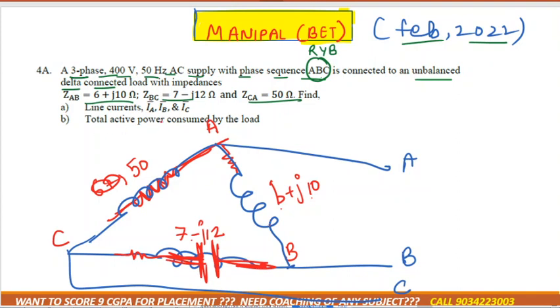Okay. Now they didn't give you the voltage, but as I told you, whenever they don't mention any voltage, that means they have given the line voltage, right? Line voltage is how much? 400 volt. And as you know, in the case of delta connection, whether it's the line voltage or the phase voltage, voltage is always the same and current is always different, correct? So can we conclude that VPH is equal to 400 volt only? But they are asking for the line current.